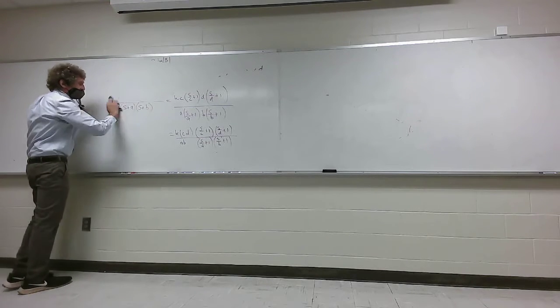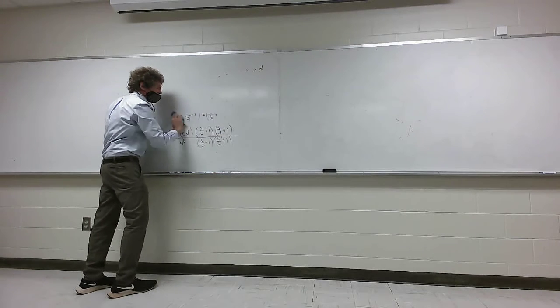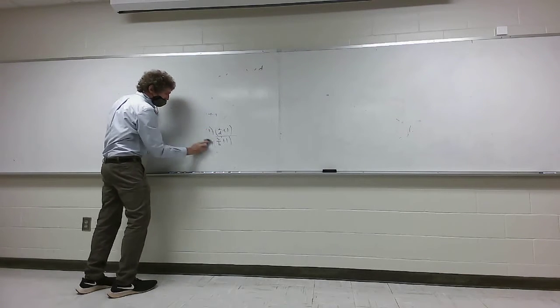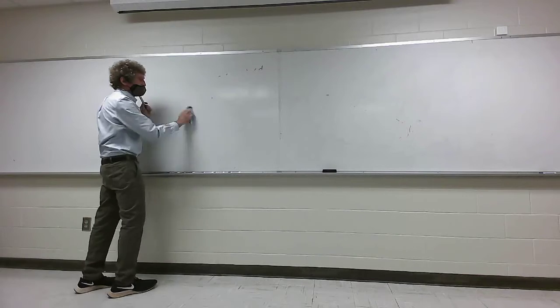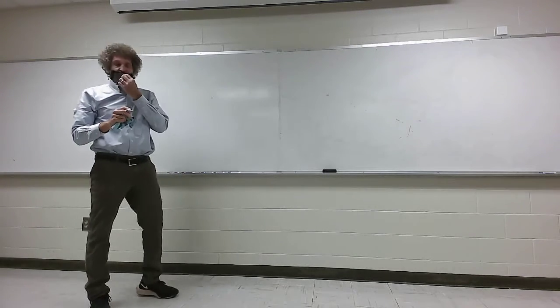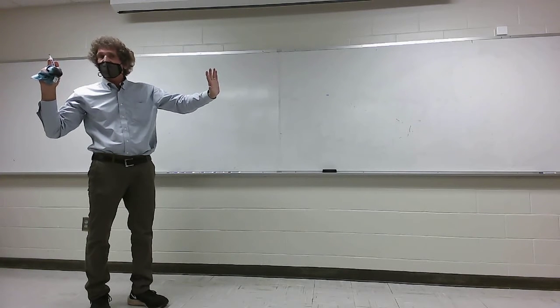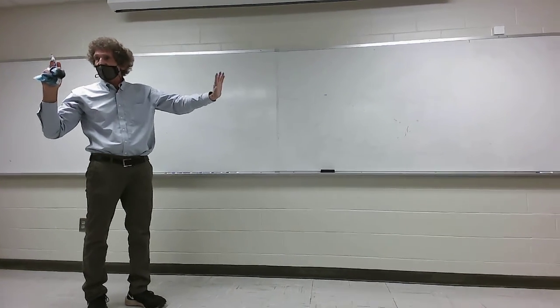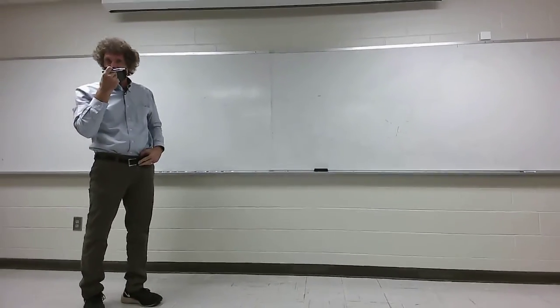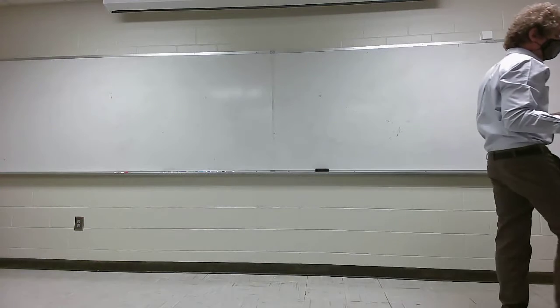But you're engineers, and I'll tell you one thing, in the real world, in engineering, most of the time when they do any kind of frequency analysis where they take all these measurements, they'll get plots. Those are exact plots. Then usually they'll try to represent them as first pole, second pole, represent them as Bode plots because they're so much easier to do engineering with. Not always, but a lot.